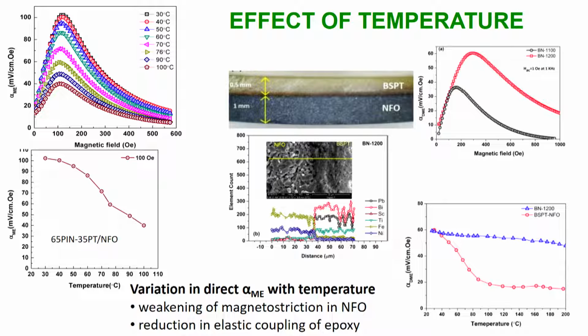Okay, so with the sintering conditions, how it is going to vary from 1200 as well as 1000 degrees, mainly because there are two different materials you are going to co-fire. Whenever you are doing that, one has to be very careful with the sintering temperature.